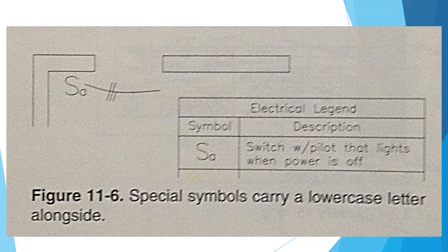Again, the lines are curved to prevent any confusion with the architectural lines. Most of these lines will be solid, the designation for wires that are concealed in a ceiling or wall. Again, they must be solid. Circuit lines made from long dashes represent wiring that is concealed in a floor, and short dashes represent exposed wiring. Any service or feed runs should be indicated with a heavy line. See figure 11-7.